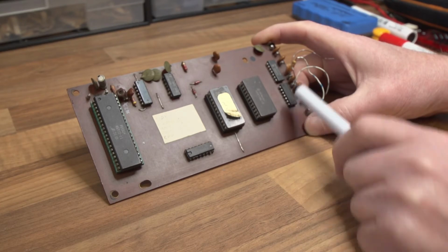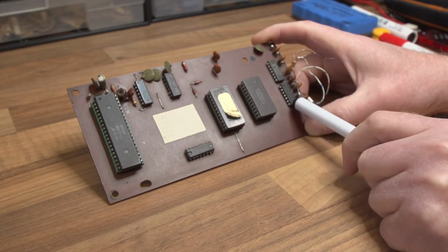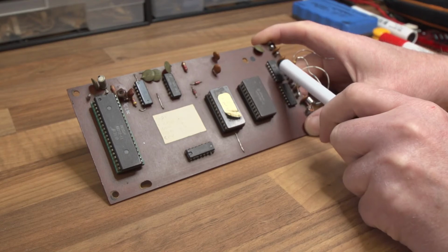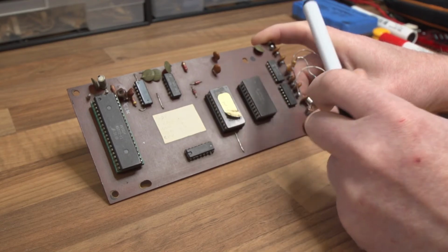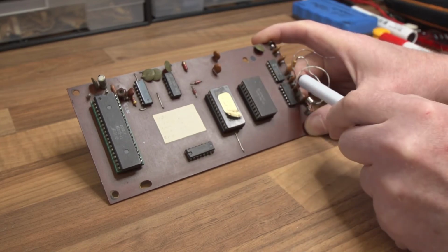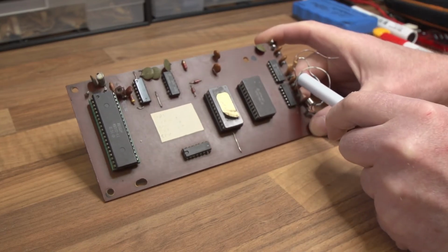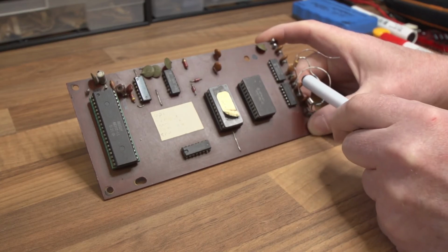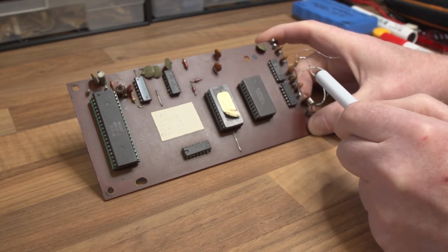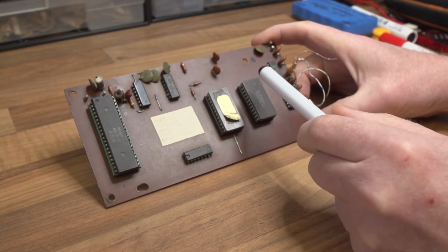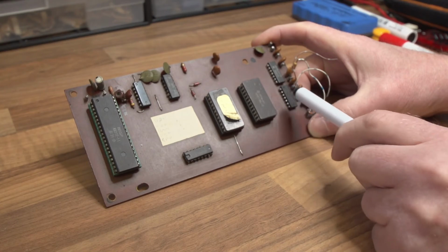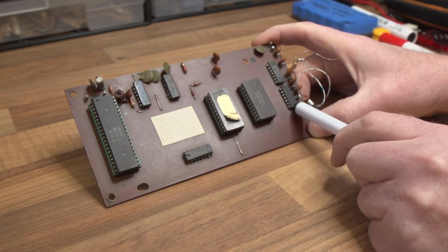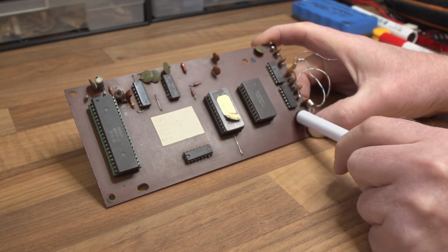We've also got a little bit of I/O here as well. We've got a couple of logic gate chips here. One is a set of what they call latches, which is basically you put a signal in and then it keeps the signal on. That goes to these pins here, which did various functions like turn the transmitter on, turn the transmitter off, send Morse code out as a digital signal, like what we call an ident signal. Another part of the I/O is the input pins. That measures other things like whether the receiver is receiving or not, things like that. There was other things as well, but that doesn't matter right now.